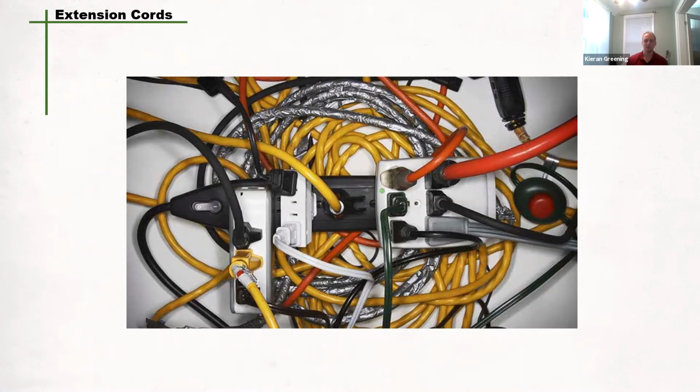So extension cords should be inspected prior to use. It goes without saying. If they're damaged and let's say you're outside working, it can become a hazard of shock with the water. And damaged cords should be removed by anyone who sees it. And then if they are going to be repaired, it should be done by a qualified or competent person. Or of course, the alternative is to dispose of it.